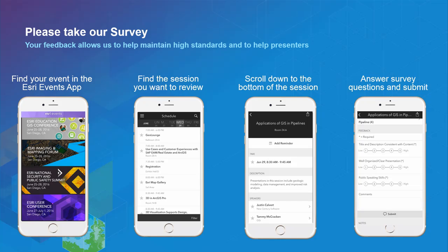The other thing you'll notice is that layer files, which are LYRX files, which I'm trying to call lyrics files, are JSON as well. One of the things I'll personally do is, if I open some project and the paths are a total mess, I can do the path repair, or I could just save it out to a mapx file, edit it, and then re-import it, and all my paths are fixed.